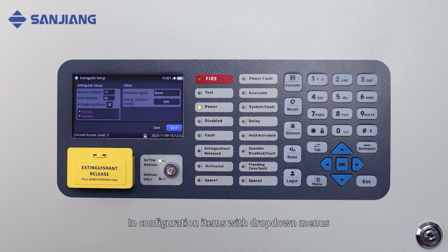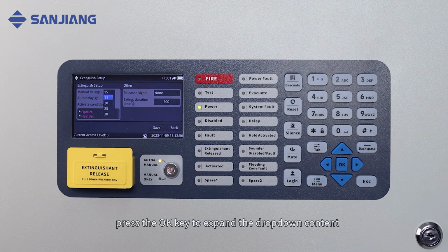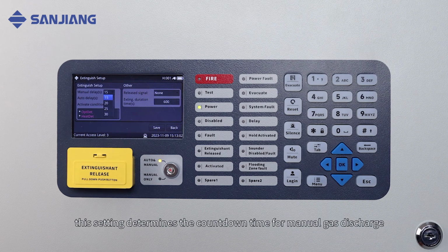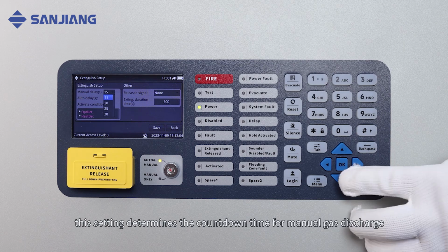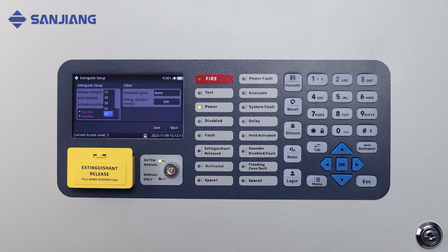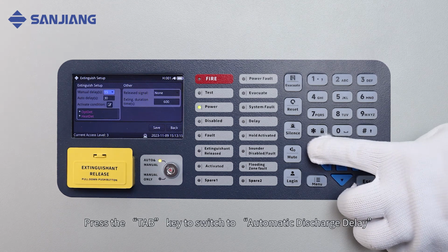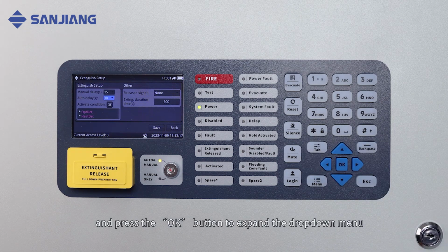In configuration items with drop-down menus, press the OK key to expand the drop-down content. Manual discharge delay. This setting determines the countdown time for manual gas discharge, ranging from 0 to 60 seconds. Press the Tab key to switch to automatic discharge delay, and press the OK button to expand the drop-down menu.